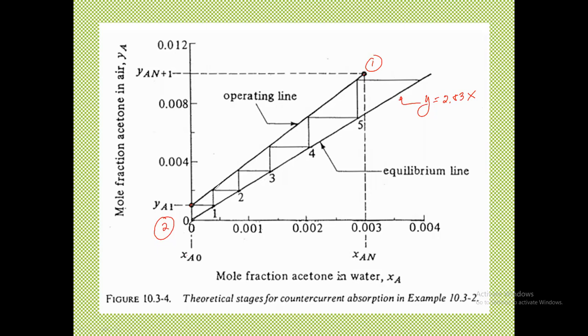So you just make stepwise lines in this manner from the operating line to the equilibrium line, like this. So this is the 4th, this is the 5th stage, and there's still another one in here. If it were to continue, it would have been like that. So you still have another big triangle here. But you're only until here, so you approximate this part. In terms of percentage, if you continue drawing, how much is this area of the entire area of that particular triangle? That would be the percentage or the decimal value that you're going to add to 5.